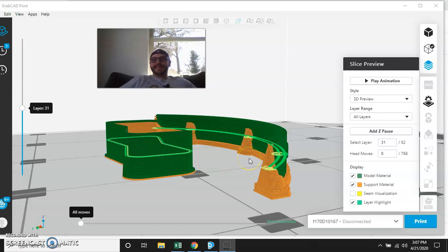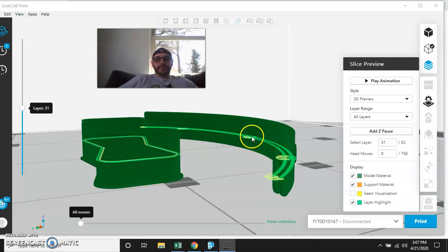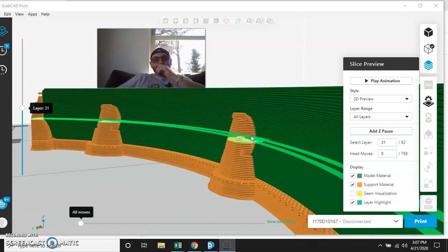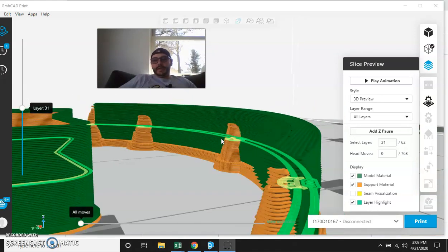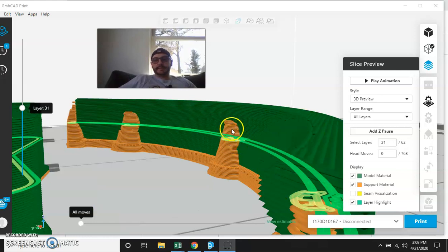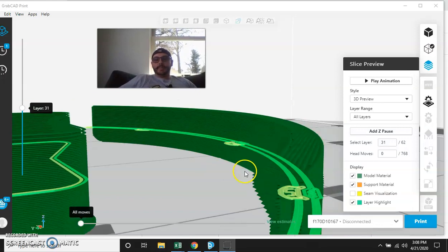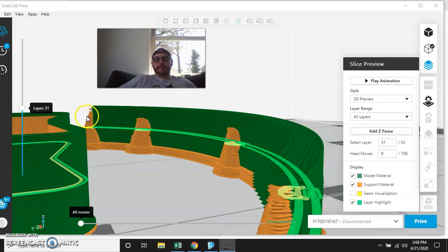Well, the problem with this design is that it is not uniform across a bunch of different printers. This printer here, our Stratus, has problems printing it in any way I rotate and orient this part. If I put this along the bottom, it still has to build up these structures, so you have layer after layer to build those bumps. Even if you come back, and this is the best way for us to print it, we may be able to break some of this out, but it doesn't necessarily work the greatest because we have all of this piece inside.